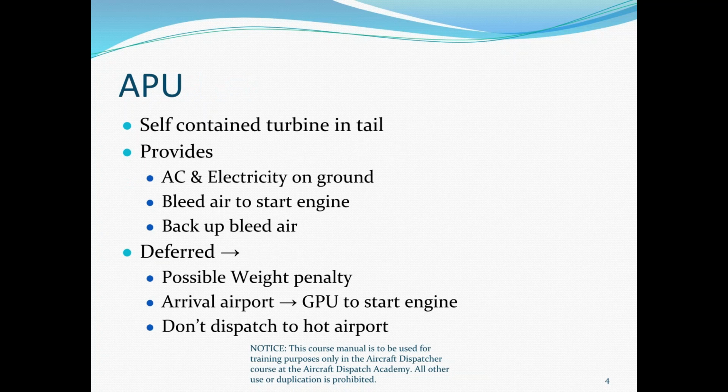APU. We've talked quite a bit about the APU, but we need to make sure that if the APU is out, then we have both IDGs. If there's an IDG deferral and an APU deferral, we can't have both. One of them's got to be fixed, right?